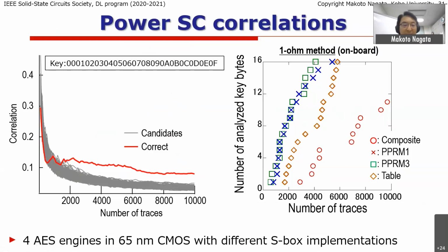One more thing, each AES core has a byte-parallel type of analysis. That means one byte stands for 256 different numbers. So among the 256 numbers, one of them can have the highest correlation with the Hamming distance or the voltage drops or the EM strengths measured outside of the die.